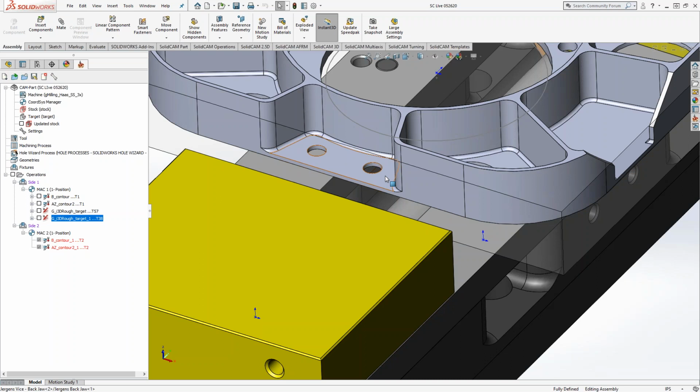It can do that. And we actually have examples of that in other videos on the YouTube channel where you're doing basically just a very deep pocket. And because of the holder collision protection and the auto collision detection in general, you're basically just going as far into the deep pocket as possible with the tool that you've selected. Then when you do your multi-tool, you choose a different tool completely, and it has more reach and it could go deeper into the pocket.